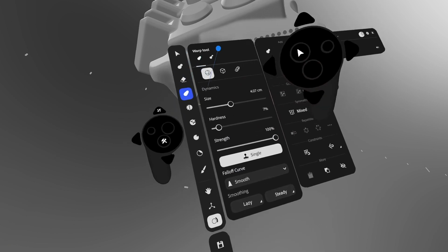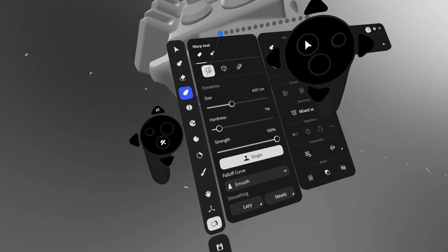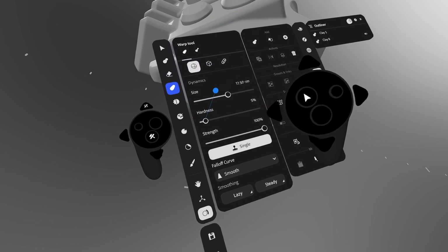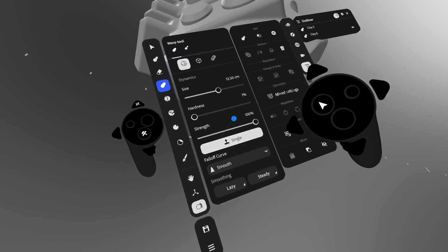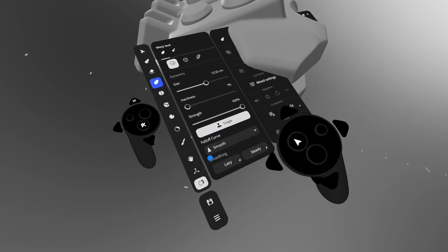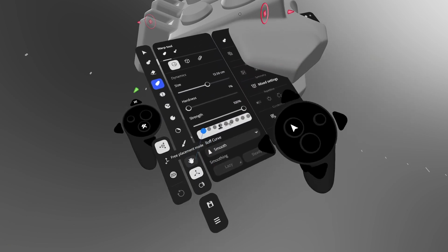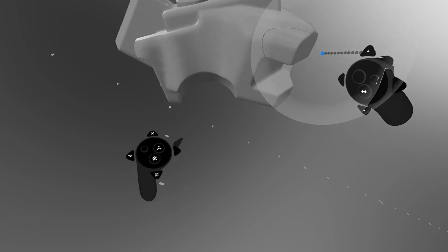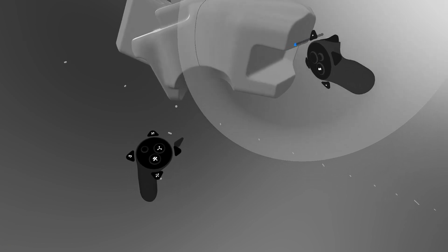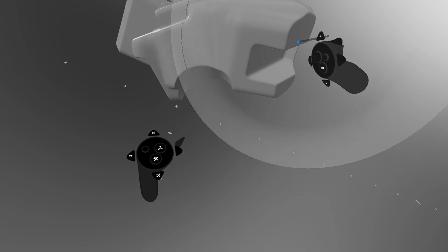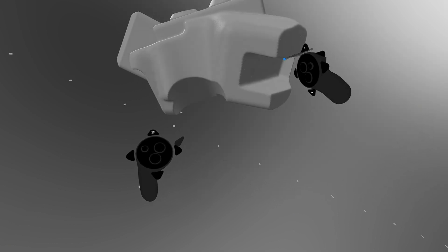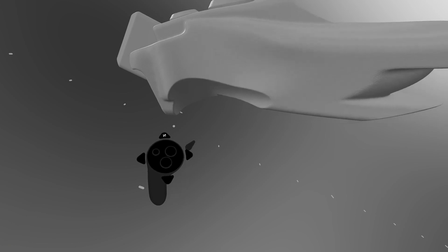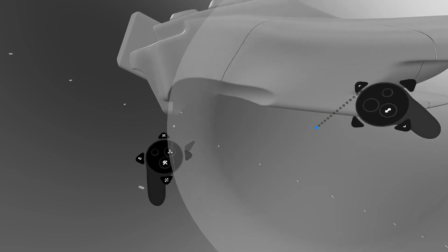Like when we go back to that warp tool, we set the sphere and we turn the hardness all the way down perhaps. And right now it's using surface. Let's use freehand, and we make it a little bit larger. We can grab most of this shape back here and pull it out like this and stretch it out, and it's going to kind of remesh it real quick.